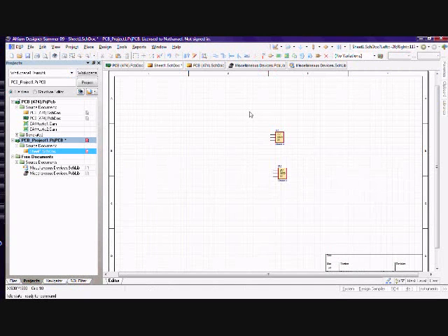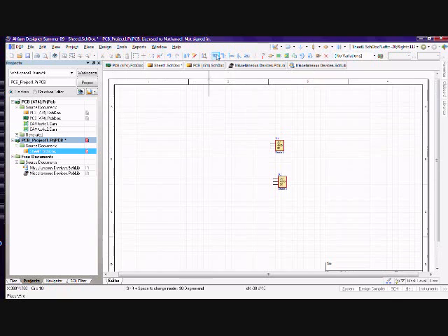Once you have the component placed onto the schematic, you will now connect components together. So you click this part, you connect in to in, ground to ground, like that. Do not worry if the wires are placed like this. The schematic will be able to acknowledge that these are 2 different pins.